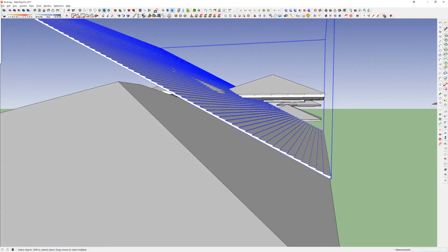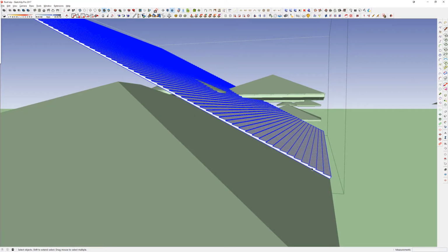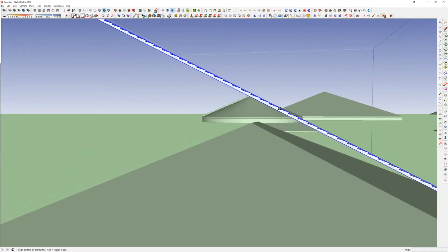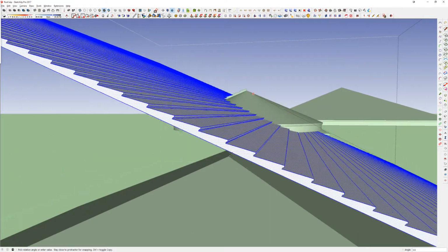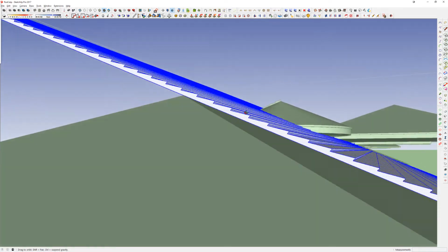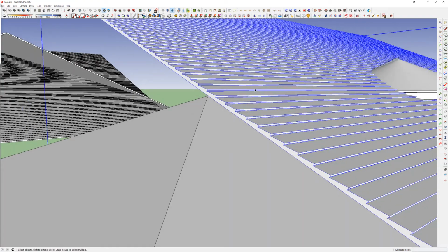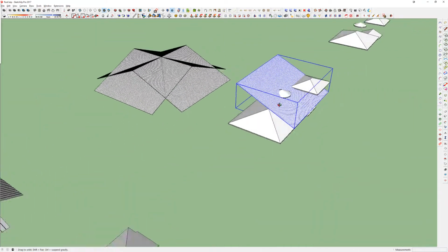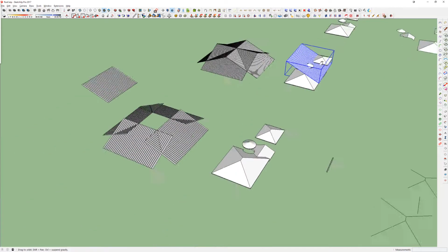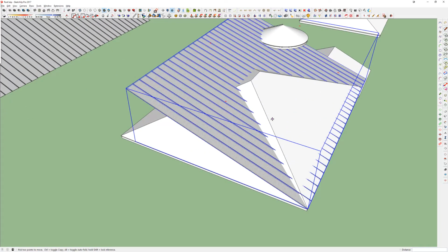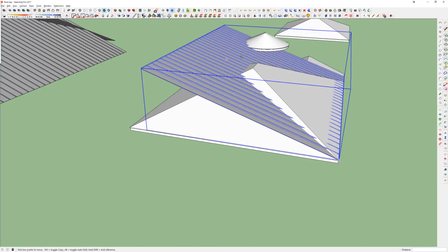So you can see right off the bat how I'm probably working on a 512 and this is probably a 612. So from here I'm going to jump inside of this group, and I'll rotate by this point here because that's exactly touching my eave, and then I'll just touch anywhere on the line and drop it down to this point, and now that gives me a perfectly sloped set of roof tile massing. And do the same thing over here. I don't need to do it a second time, but this one you see is coming in as a 412, and I'd basically do the exact same process and make this into a 512.